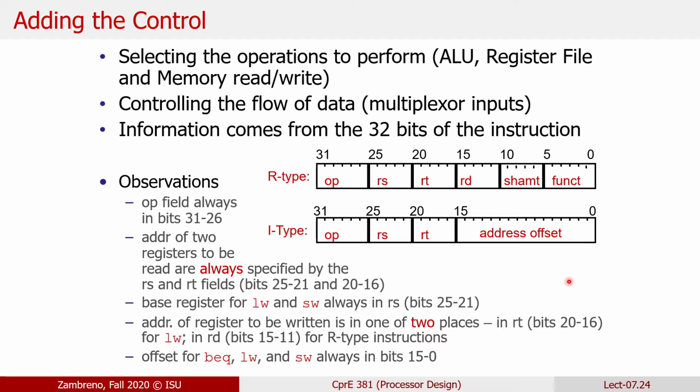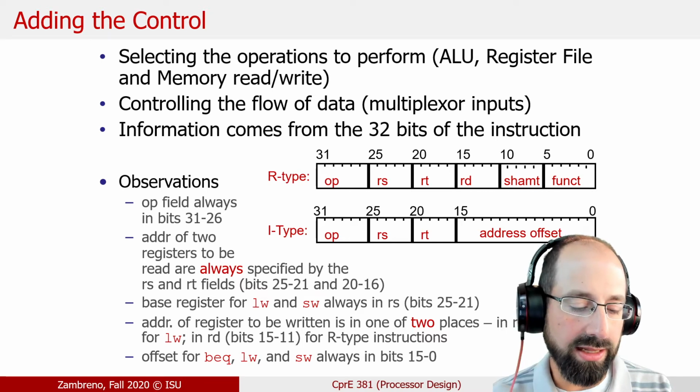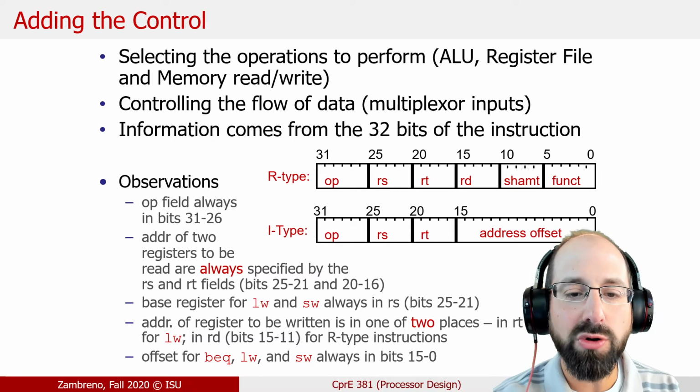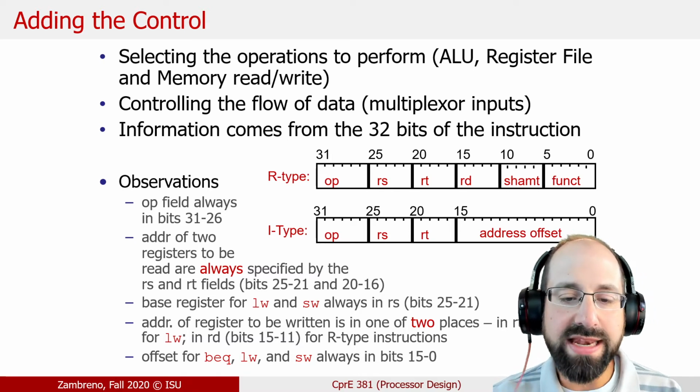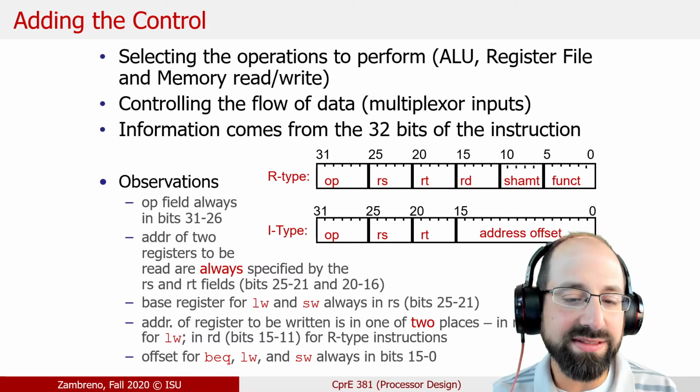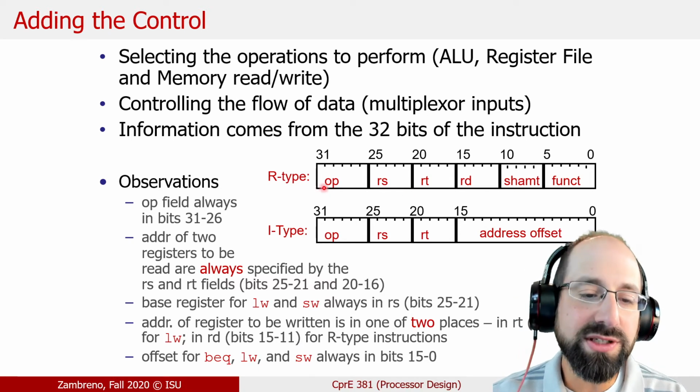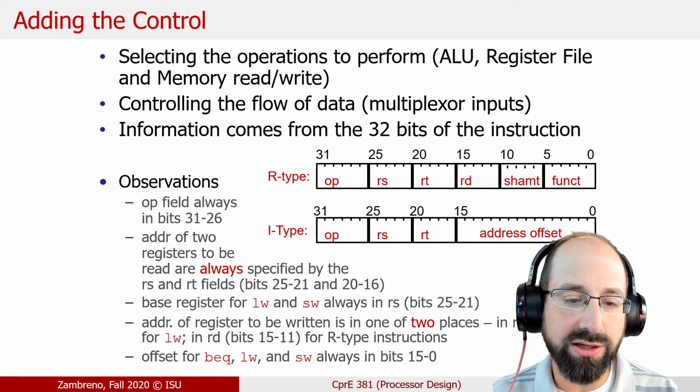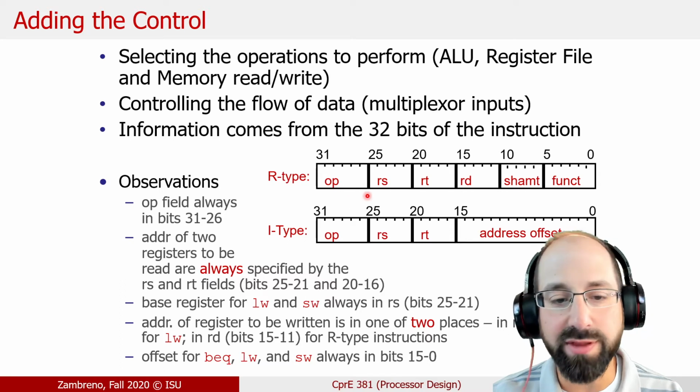But we know it's actually the instruction encoding itself that dictates that mapping between things like our opcode field and our resulting control signals in our design. And that's why I keep talking about the lookup table based approach or the Excel spreadsheet based approach to designing our control. The nice thing about MIPS, this is part of the MIPS design philosophy, is that so much of that information can just be directly encoded in those 6 bits that we have there.